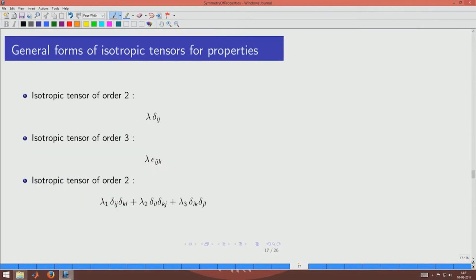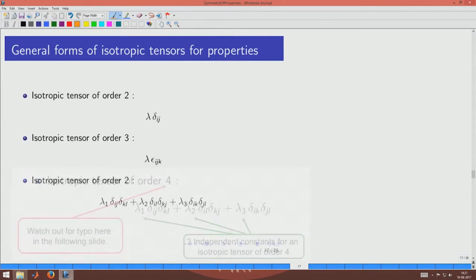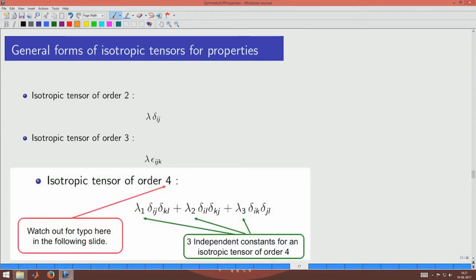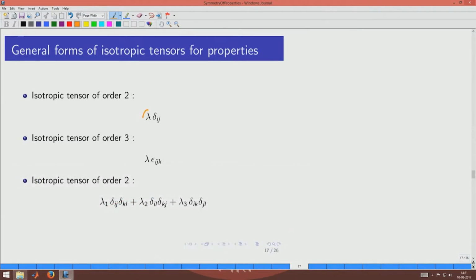Okay, so, whenever we have isotropic materials like gases, liquids and polycrystalline materials, if you have a second order tensor quantity that has to be represented, then you just use only one number, and you multiply with the Kronecker delta, which is an isotropic tensor of order 2, and then you are done with that. So, if you are talking about the thermal conductivity of a liquid, then you could write in this manner.